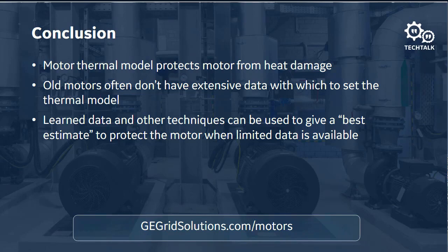Yeah, so here's a great question. The NEC states that if the motor service factor is 1.15, you can put an overload factor up to 1.25. Is that the case with GE relays? So yeah, the NEC states that you've got to oversize your motor leads, and that's usually at 125%. So you don't want your thermal model to exceed 1.25. You'd never want that. If your service factor is 1.15, you could go up to 1.25.